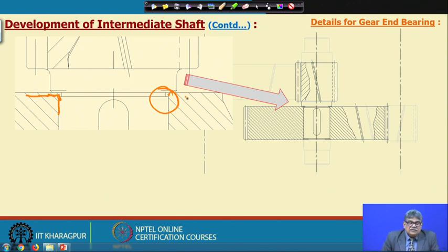Here I would like to mention such an undercut is given by a special tool which is available, which is kept aside, and it is put on the multiple or turret type tool stand, and then this can be given. This is simple, maybe 2 millimeter thick. Apart from that, suppose without this undercut, your iso-stress curve may go like this.